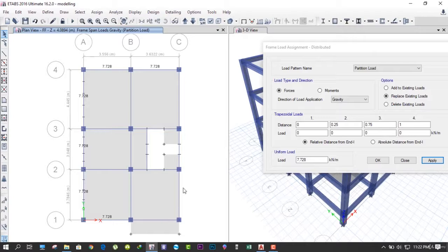Okay, and now we select these beams over here. Okay, so this one also. And what we do, we apply the load as 19.2 into 0.23 into 2.50. Okay, so we apply and we again go one step up, and here you got open terrace on this portion over here, so you don't have any wall, right? So we apply in these two beams only.